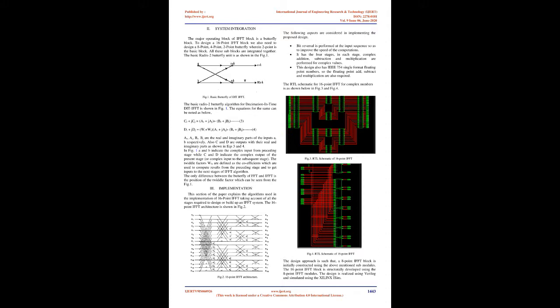In this paper, the implementation of the IFFT block utilizes the decimation-in-time, DIT, Radix-2 Butterfly unit, which has complex adders, subtractors, and complex multipliers. All these are further integrated. The Radix-2 Butterfly unit plays an evident role and is considered to be the heart of any FFT or IFFT processing algorithm. Hence, the working of the Butterfly unit is predominant in the IFFT processor. The proposed work includes the implementation of a 16-point IFFT for complex numbers as well as floating point numbers, with their verification. A general IFFT representation.